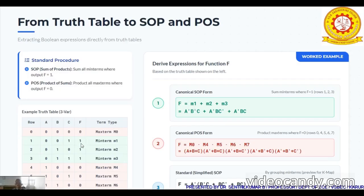So if a 1 is available here, the corresponding row 1 should be taken, M1. If there is another 1, the corresponding row is M2. If there is a 1 here, M3. All other outputs are 0, so they are omitted. The M1 value we already discussed in the last slide. If M1 is there, it should be taken as A bar, B bar, C. For M2, it is A bar, B, since 1 is there, we take B as it is, and since it is 0, C bar.